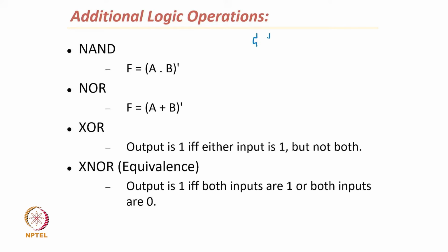We had two PMOSes in parallel on the top and 2 NMOSes in series on the bottom. This is A, B, this is A, B, this is the output.